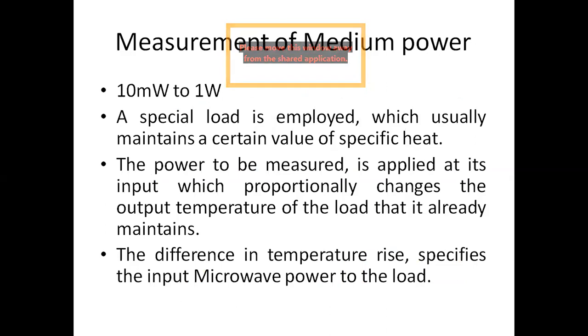In RF and microwave, 10 milliwatts to 1 watt is considered medium power. How we measure this medium power is, generally, we introduce a special load on the path of propagation of the microwave. The power measured is proportional to the change in temperature of the load.